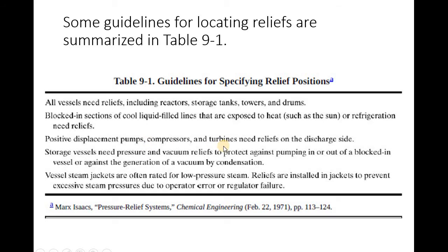Positive displacement pumps. So you have pumps, compressors, they give us pressure. And because they give us pressure, they need reliefs at the discharge side. Of course, the discharge side, I did not explain this, but if it comes to your mind, why is it not the input? Because the pressure is at the output, right? So you always need reliefs at the discharge side.